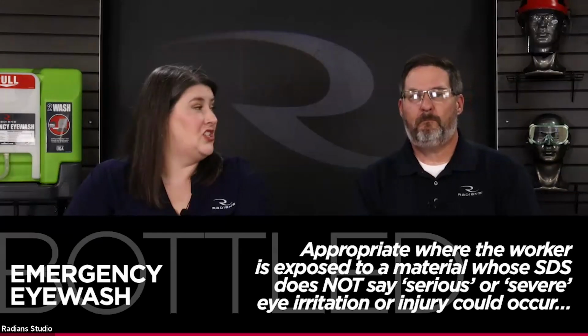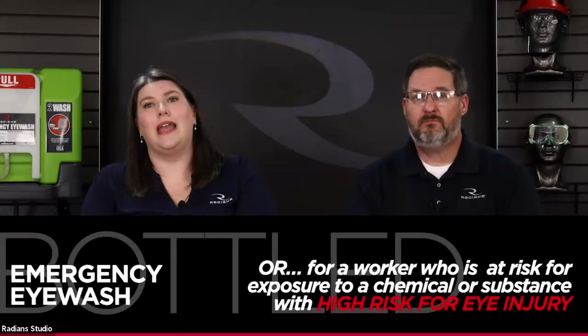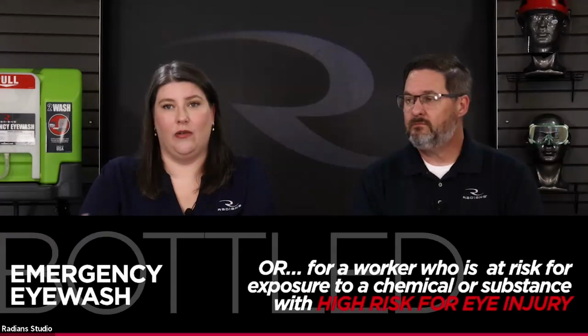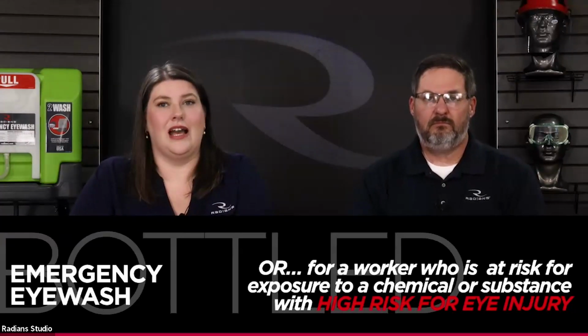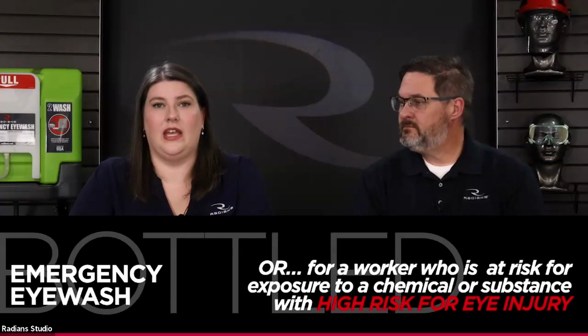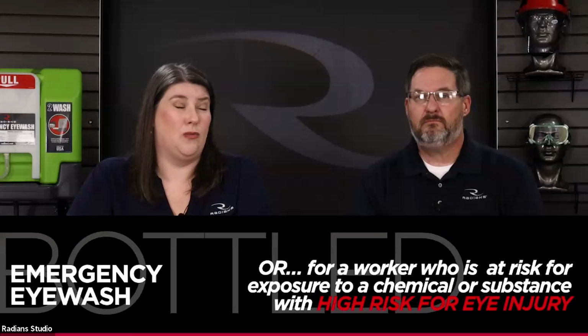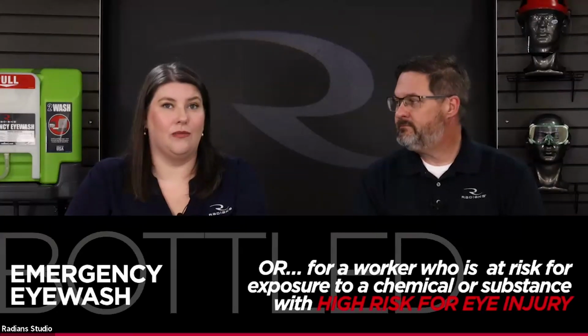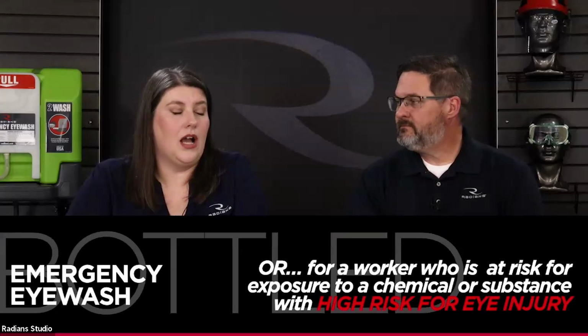Yeah. What about a bridge-the-gap situation? That comes up too. Yeah, absolutely. So maybe the SDS has very clearly said we need an eye wash station, but the substance being used is highly caustic, highly corrosive, and can begin causing permanent damage to the eye, not in that 1 to 5 minute time frame, but within seconds. And a lot of chemicals do fit this bill, right?